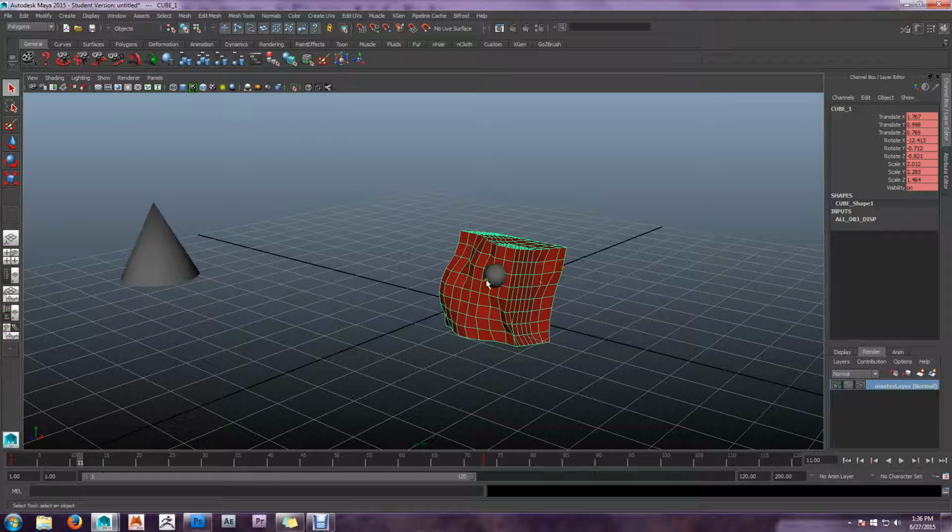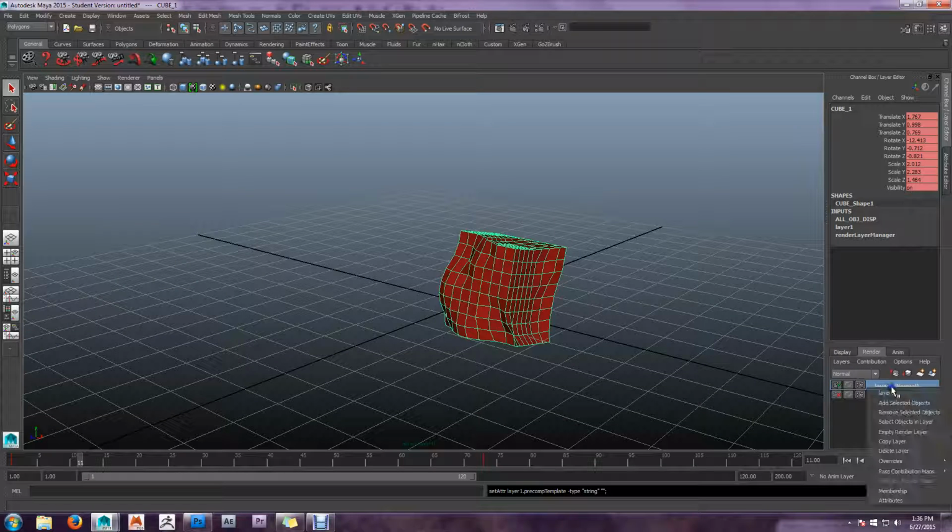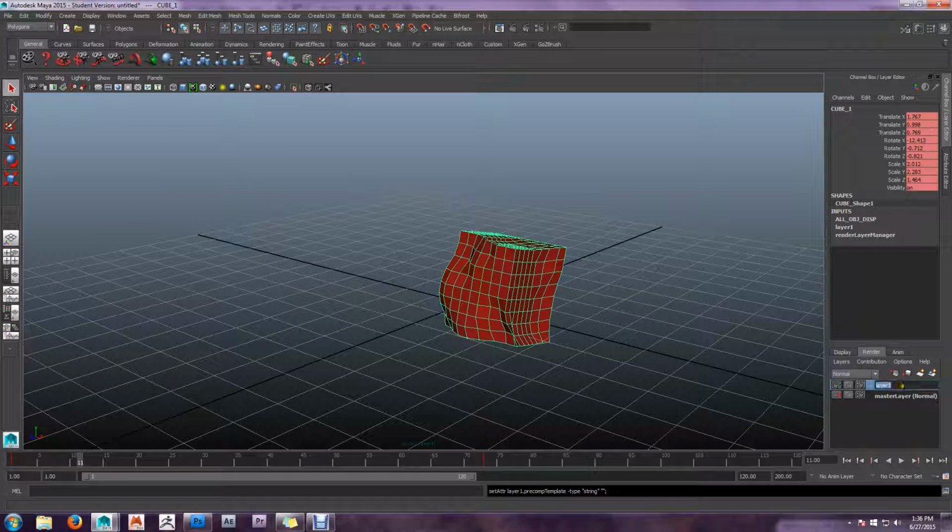You would select certain render attributes of the object, and you would create a new render layer, and you would call this layer shads for shadows, and then you call another layer highlights.